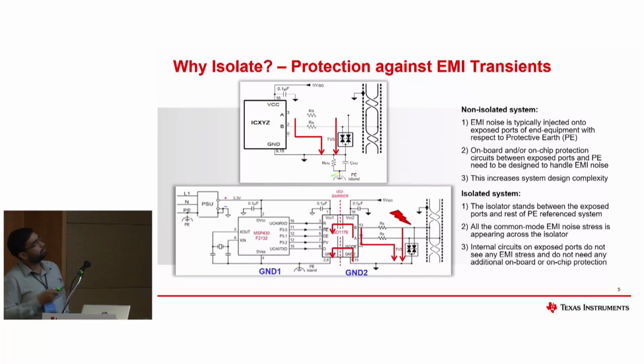So what you're seeing here is RHV, CHV kind of resembles the isolation between the device ground and the protected earth ground, but this requires a whole lot of design complexity, and the ratings, the standards that the international body requires cannot be guaranteed in this one.